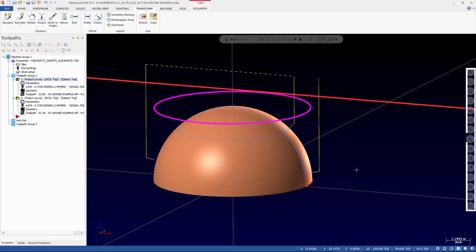And there is some additional functionality like OptiPath. So some of the functionality that's in Vericut allows you to optimize your programs by detecting how much engagement of your cutter is happening and allowing it to actually vary the feed rate throughout the program, and also do things like speed up the air cutting.